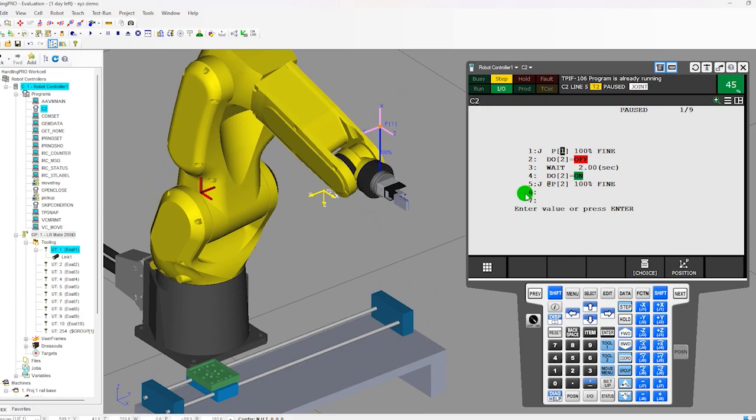What if we want to program the robot to a position, but using the real teaching pendant? Basically, in the software, you drag that TCP, that sphere, to a position. In the real world, you have to use the keyboard of the real teaching pendant to operate this machine.